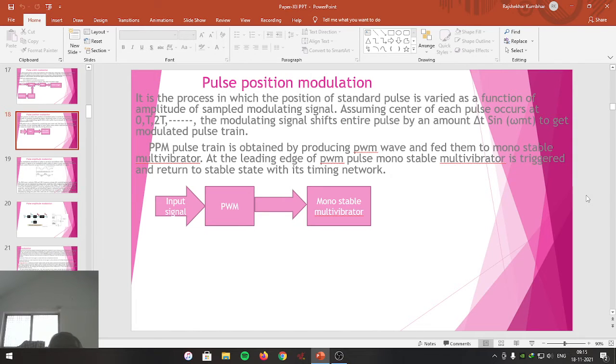That means the analog signal is clamped by introducing a DC bias, and then its samples are taken at different intervals of time. After taking the samples, they are given to the quantization level for rounding, and then they are encoded after compressing the signal to reduce the bandwidth and to improve the quality in transmission.